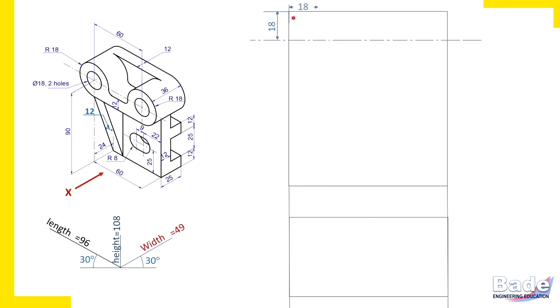Now measure 18 mm. From left, center is 18 mm. Also from right, center is 18 mm. So locate those centers first. Similarly here, from right 18 mm, and I have drawn the center lines. So this is how we have located centers of these two circular edges. So this is how complete circles, and there are holes also.